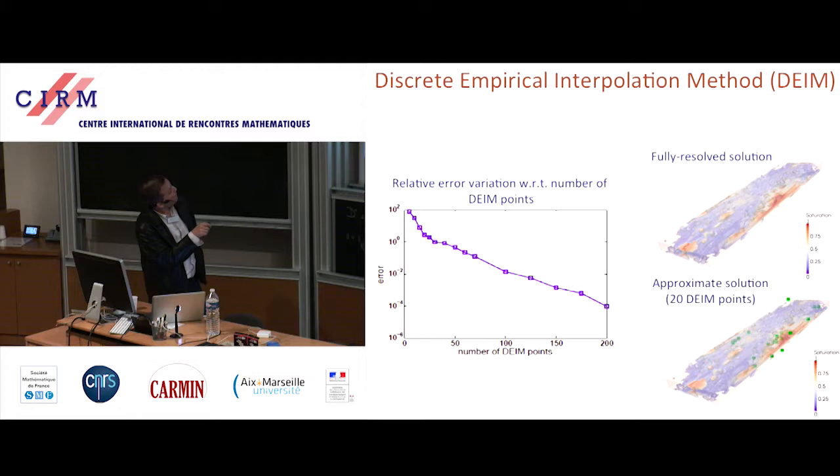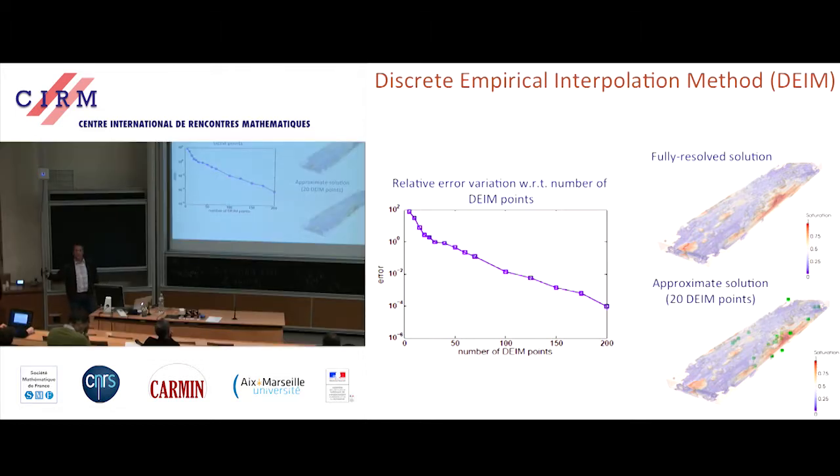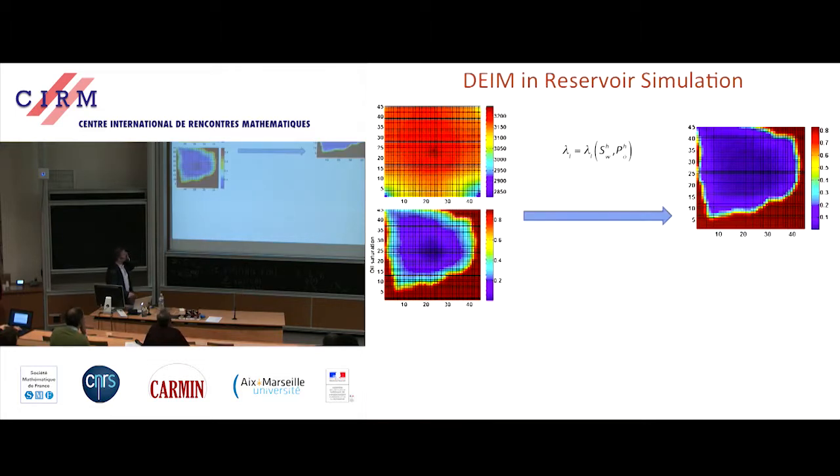When we apply this to our multiscale problems, what we can do is compute the global modes that we have used, either POD or dynamic mode decomposition, and evaluate them at, say, 20 positions, and the 20 positions are these red dots over the whole domain. And what we can see is that if we evaluate these DEIM points, with 200 points over the domain, we obtain an error of 10 to the minus 4 on the residuals and the Jacobians of the system.